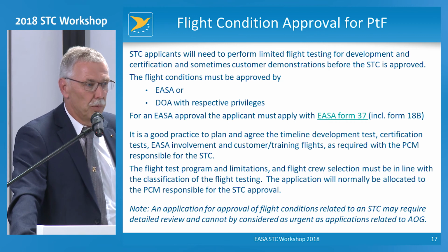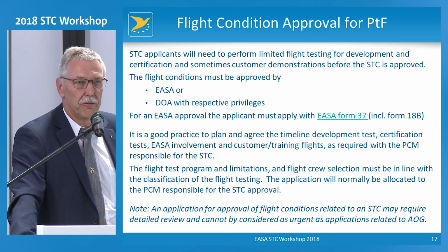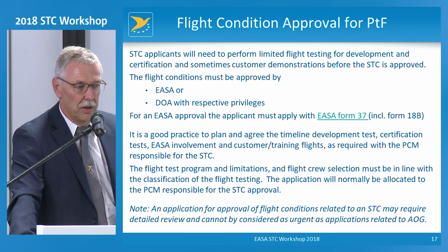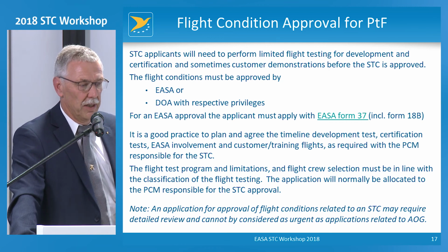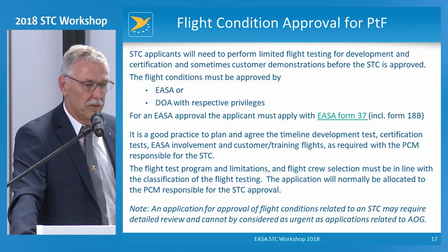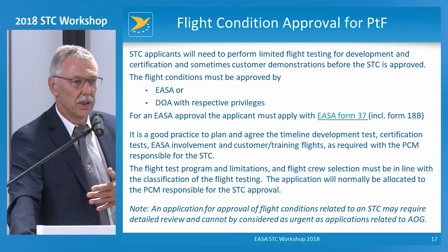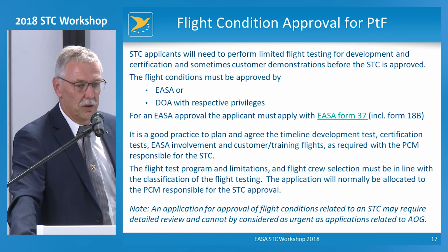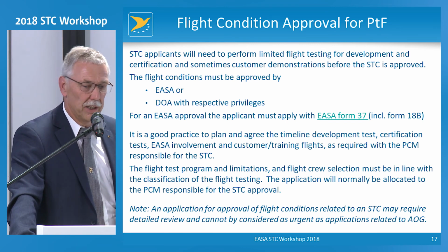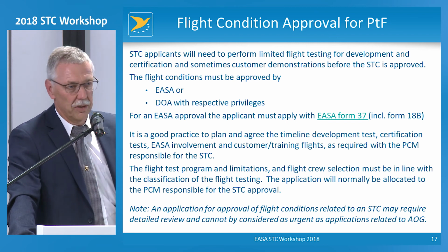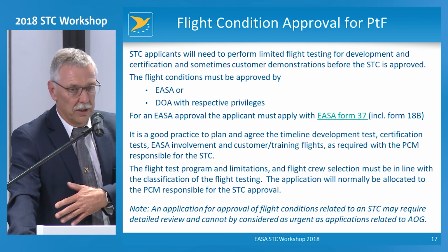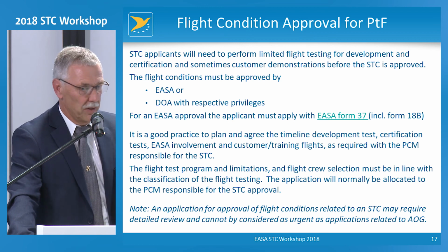One interesting point I wanted to make is that if many modifications are in the installation process of an aircraft, possibly two STCs at the same time which are not approved, there can only be one flight condition for the aircraft. It doesn't make sense to have a flight condition on one system and another one on another system and put them together.